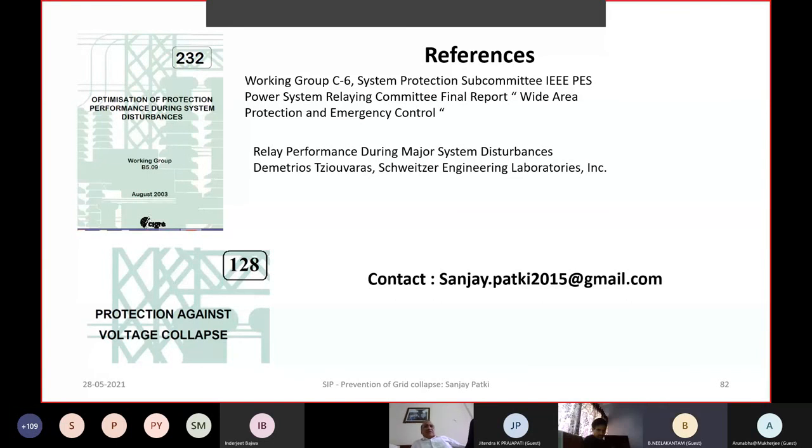No, sir. As per the Ramakrishna Committee guidelines, it is zone 2 at 350 milliseconds. Correct. Prior to that, you are right, sir. It was given as 1 second, and the reverse zone setting is 50% of the shortest local transmission line, sir. So I think wherever it is not adopted, we should adopt the recommendation which was given by the Ramakrishna Committee.